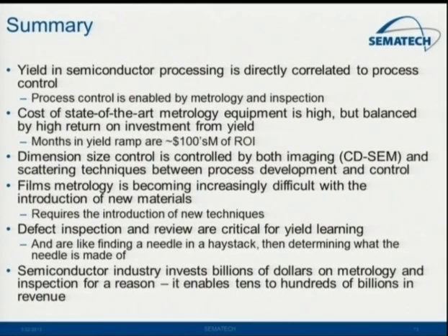Dimension, size control, we have two methods. Either we try to image the surface, where we pull out a lot of two-dimensional information, or a scattering technique where there's a target that's deliberately designed to measure the dimensions. We measure a lot of film techniques. As we introduce new materials, we've gone from all optical. When people were looking at silicon dioxide, you used only optical techniques. As you go to these complex high-K gate stacks with hafnium oxide and lanthanum and tantalum nitride and tungsten and all these other films in there, you have to start introducing X-ray techniques or others.